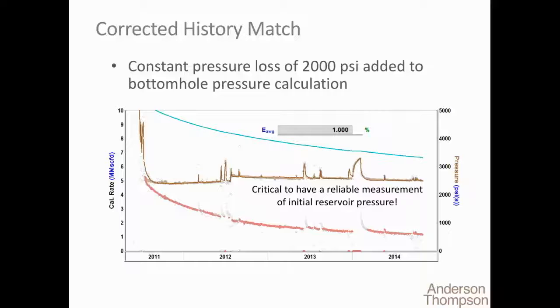We had discussions over initial reservoir pressure and whether that could be validated. In this case, there was a lot of evidence to support the PI. Therefore, there was something going on in the bottom of the well that was causing a pressure restriction. And in this case, this well, I believe, had jewelry left behind. They could be unmilled out ball seats. It could be a number of issues. That certainly might not be the issue, but a variety of issues could cause this.